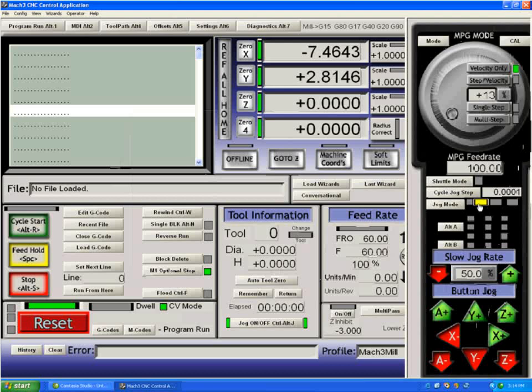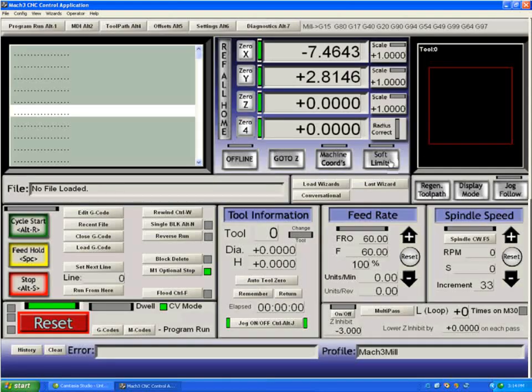So if you look at this screen, the second LED here should be lit, indicating that you're in normal keyboard jog mode, and you should have a jog speed above 5%, and you should see movement. Hitting the tab key will make that jog screen leave the screen. So at this point in the program, I can now jog, my motors are moving, and if you've tuned them properly, you should now have some pretty good movement with them.